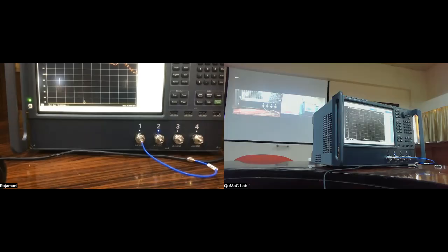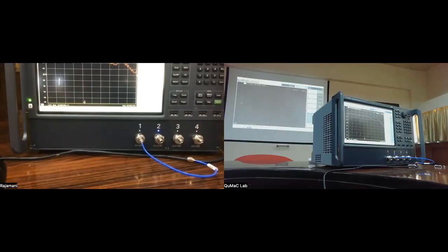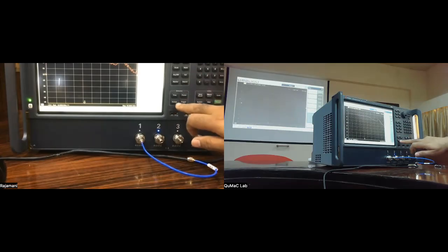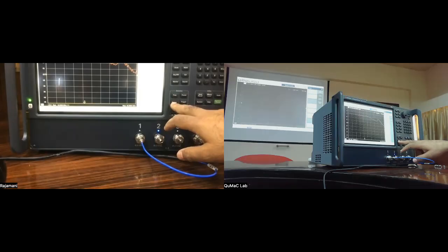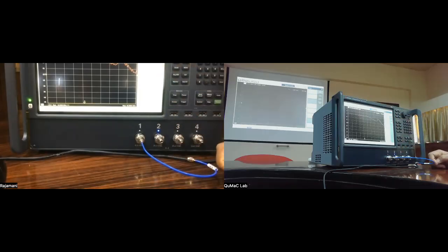But as always, the things you have to set, I'm going to shift to the VNA display. So the remote people might not have the greatest view because of the video contrast of the background image. But again, just to remind you, typically you start by setting the frequency range, start frequency, stop frequency, set up the sweep. Right now it's set to 201 points. You can set the power.